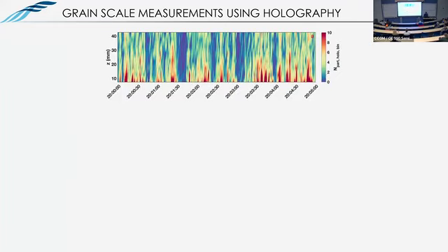So there are some pretty cool things we can do with this, because not only can we identify individual particles, but we can do image analysis to pick out the size of those particles and do shape statistics on them. So here is a time series, just 5 minutes, measured at 10 hertz, of the number of particles above the bed over just a 35 millimeter section.